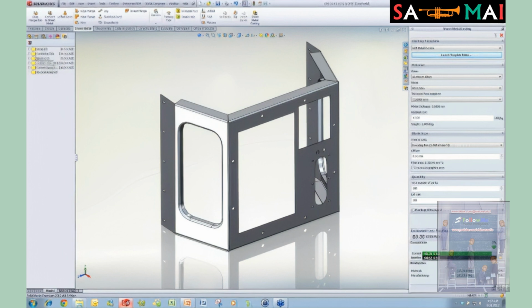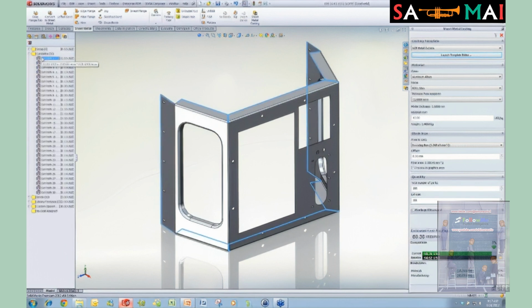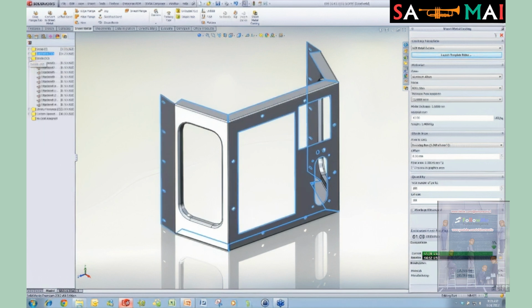We can also come in here and say maybe these cut paths are a little bit different. Maybe we don't want that to be maybe one of these holes. Maybe we don't want that to be laser cut. Well, I can right mouse click on that, and instead of laser, we have some different options. We could come in there and I could water jet it. I choose water jet. You can see the price of it, it's a little bit more expensive. Instead of 1 cent, it's going to be 2 cents. All right, well, maybe that's a critical hole, or we want to use water jet on that for some reason. And I can increase the price, and now I'm at 5% cost. We can take this one and we say we could plasma cut it, whatever we want. The bins, all right, we could put on a different bin machine if we want. Change it like that.